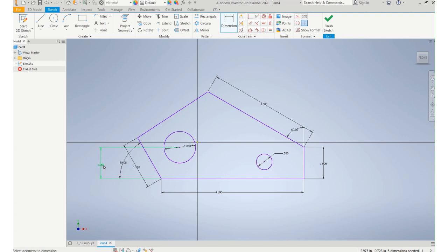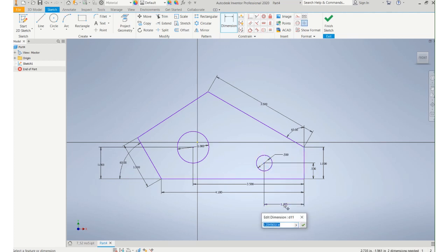Now one thing you'll notice is the dimensions on the sketch don't show up on the drawing sheet. So you can actually use poor dimensioning practices in terms of locations of the dimension. I'm just programmed to not do that, but as far as dimensioning on the part and so forth, it's okay. Part of the problem with doing that though is that it really clutters up the drawing, so it's really advantageous to use some decent dimensioning practices when you can.